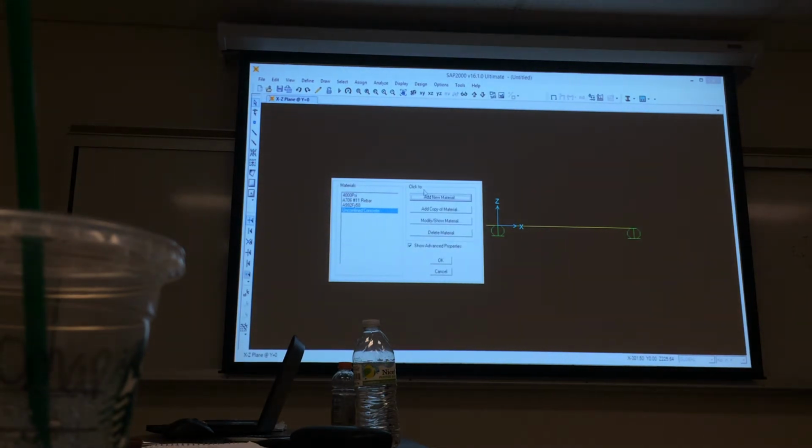Likewise, we're doing the expected yield strength. In homework 5, we use 68 KSI. Or in the case of our rebar, I think it's actually like 72 or something from the test data. Right, you want to use your actual test data. So Caltrans, if you use those guidelines, they basically say if you don't have any test data available, these are the acceptable values to use. But if you do have test data available, you want to use the specifics of your test data.